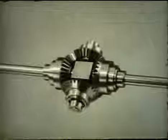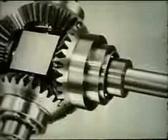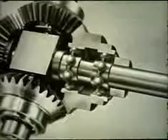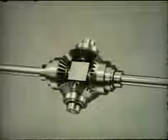None of these four gears is fixed to its shaft. Each gear is freely mounted on bearings as shown in this cutaway. Connections to other mechanisms are made through spur gears, one lock to each end gear and one lock to the spider shaft. Additional gears and shafts complete the connections.